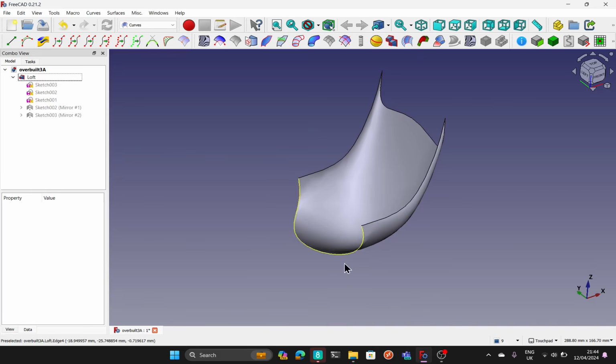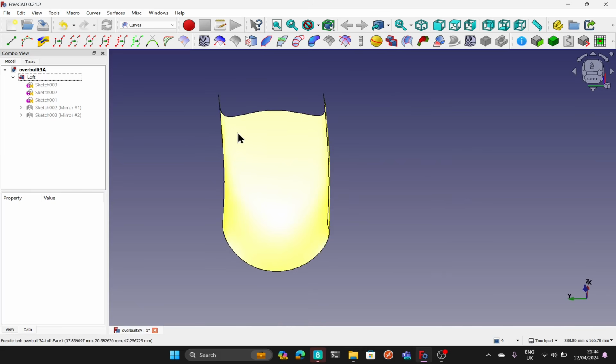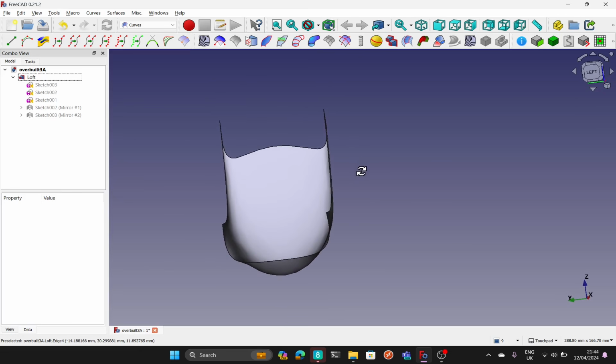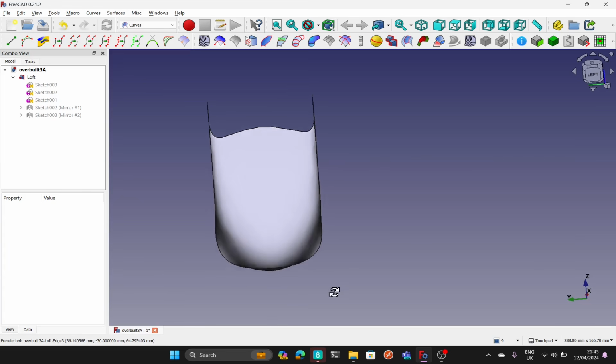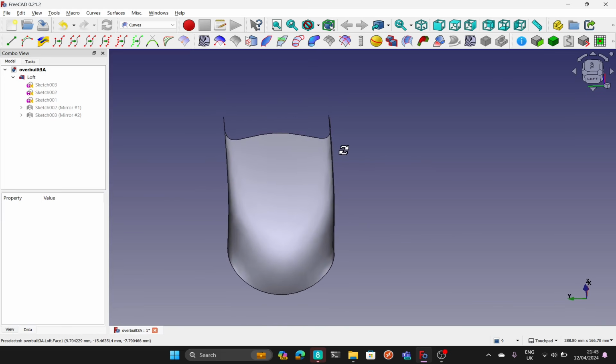And what I want to do is find a projection that allows me to create a sketch on this surface. Because if we look at this, if we create a projection from here, so if I create a sketch upon the YZ plane, then if I created a slot going through this object, then it wouldn't be projected into the base here. So we need this face onto the camera.